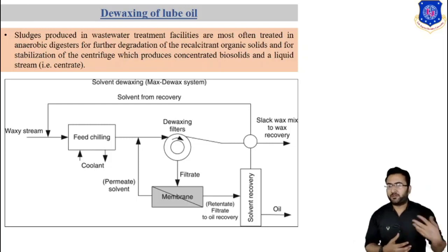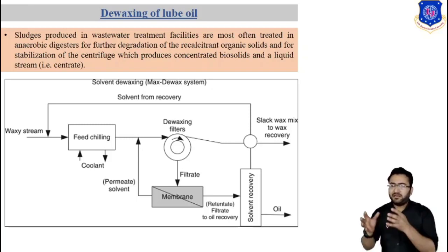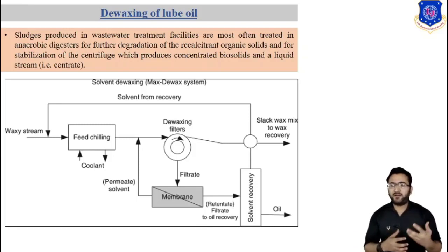However, subsequent solvent recovery by flashing and stripping incurs a high cost. On the other hand, a reverse osmosis process employing a silicone rubber membrane can yield better separation. When fluorinated siloxane polymer is used as the membrane material, high flux and better selectivity are achieved.